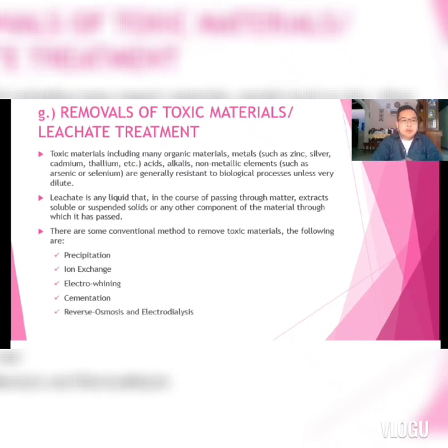Next is reverse osmosis and electrodialysis. It involves the use of semi-permeable membranes for the recovery of metal ions from dilute wastewater. In electrodialysis, selective membranes or alternating cation and anion membranes are fitted between the electrodes in electrolytic cells, under continuous electrical current.